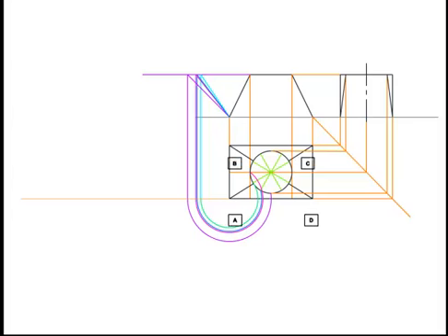We label corners A, B and C. This will aid in the development process. We also label 1, 2, 3 and 4. It is very important that you note 1, 4, 2 and 3 in the sequence they occur, because in plan line 4 is rotated and actually gives us a longer distance in elevation. This is very important.